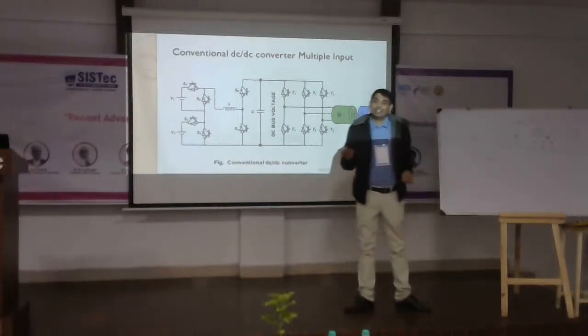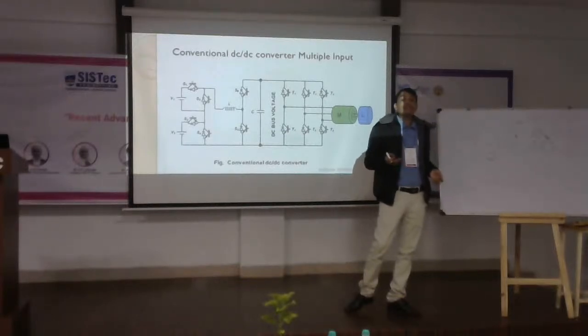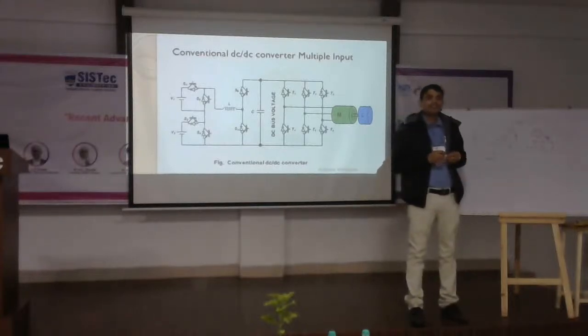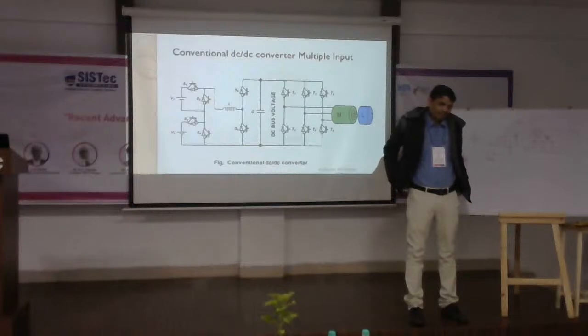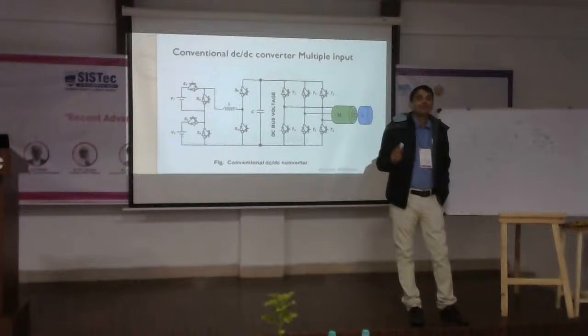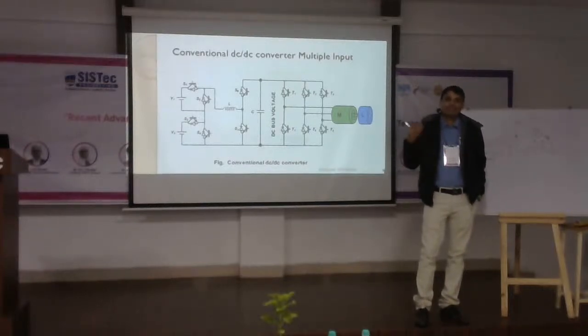Okay, for variation of the DC voltage, there is no possibility without connecting a resistance. If you want to vary the DC voltage, how can you vary it? Is there any provision? You must have studied this in third semester. How can you get the variable voltage? Okay, so there is no provision without connecting a resistance. When you connect the resistance, there will be a drop. Simply, that is a voltage divider circuit you can use for reducing the voltage. So there is no direct provision.